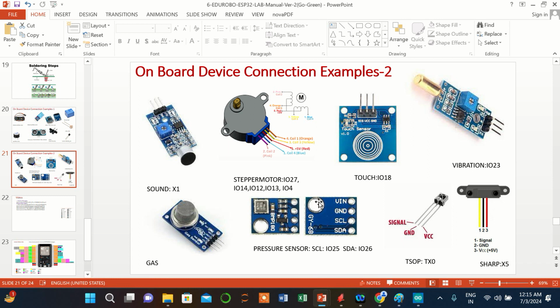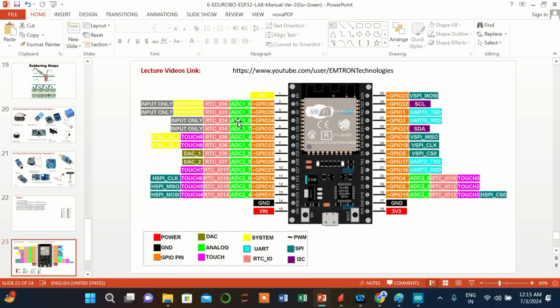And then in a subsequent session, we will try analog sensors also. The difference is when you use analog sensors, you won't be using GPIO pins. You have to use the ADC pins, and it's not a digitalRead. It has to be analogRead, and you mention which of the analog pins, these green colored pins, you want to read. And the A to D converter has